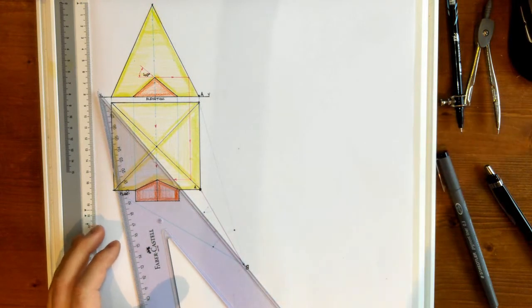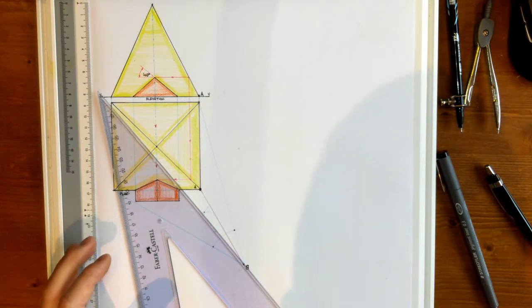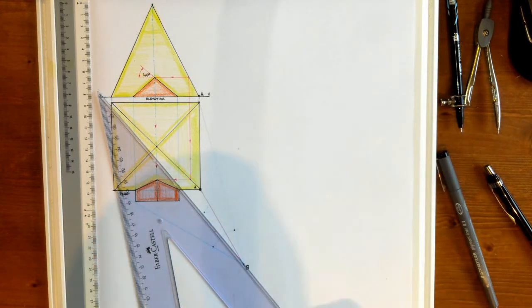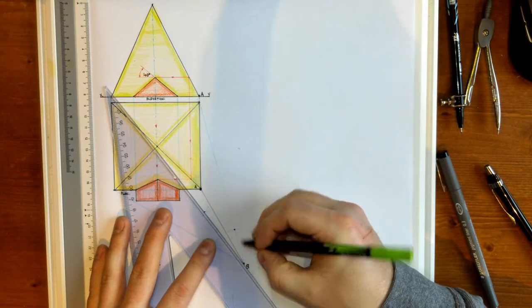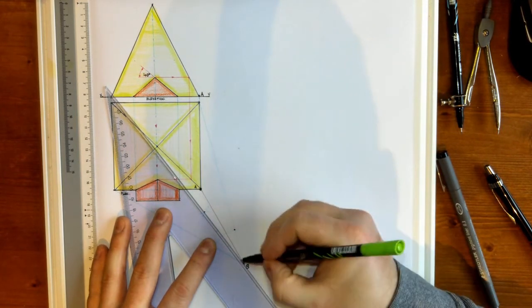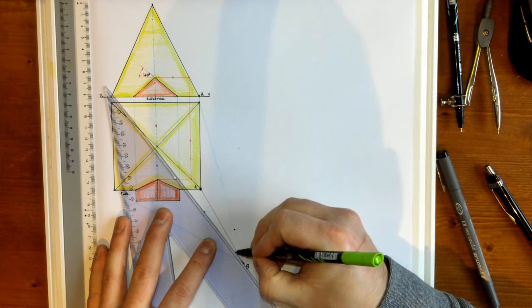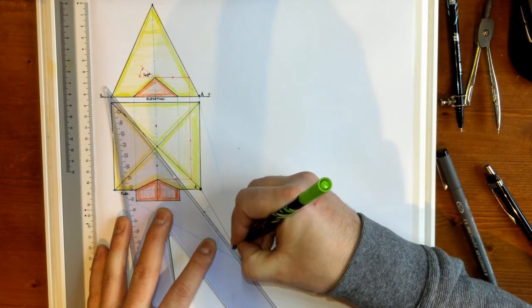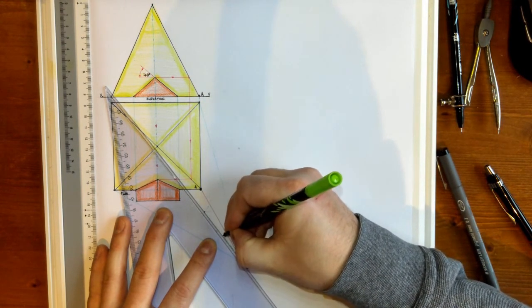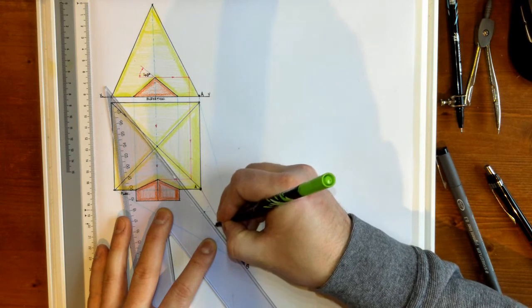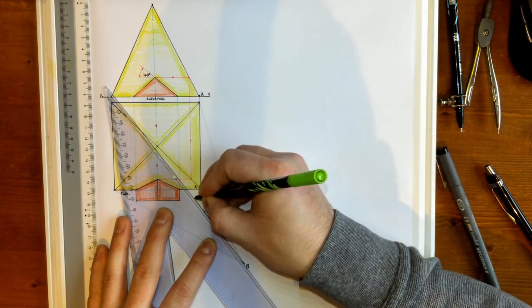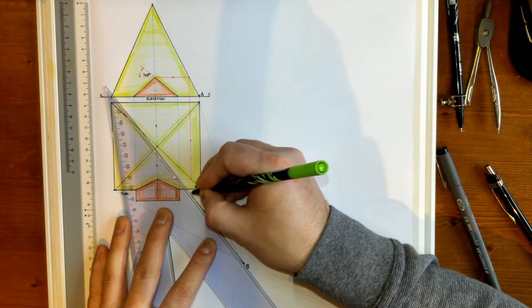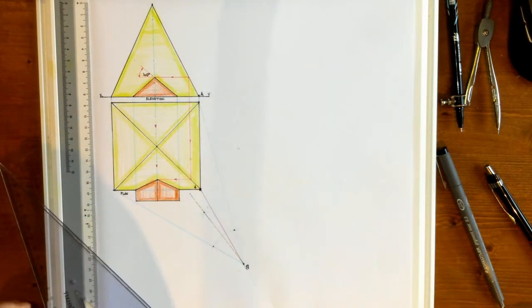So we'll use a different colour for that. We can take a little bit of green and we'll run with that. So from S now, through the bisector point to create the bisector line. Okay, now I might put that in as a dashed line. It's not hidden detail or anything like that, but just so we can differentiate between that line and the other lines that are there. And I'm just going to roughly draw it up as far as there.